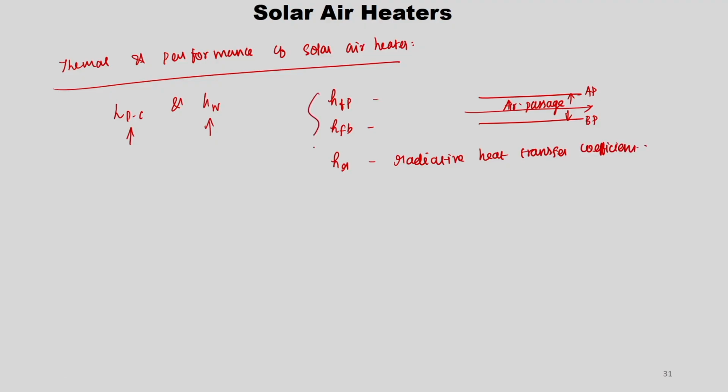Using these three, there is another heat transfer coefficient, which is the effective heat transfer coefficient. So, this is nothing but HE = (HFP + HR) HFB / (HR + HFB).